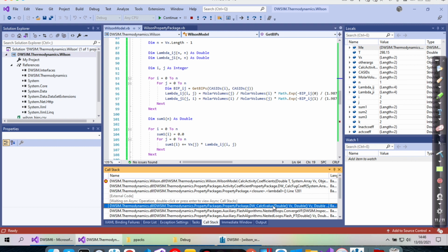This is a very, very common situation when you do RTO, real-time optimization, because you need to use plant data that contain errors. It means it would be interesting if we can bypass this test, saying, hey, don't test this liquid because I know that it's liquid, because it's at the bottom of the equipment, and use the temperature, even if it's overheated liquid, I don't care, because it's what it is. You know, sometimes the thermodynamics contains errors, by the way, and maybe it's underestimating the temperature, and the actual plant temperature is just a little bit higher.